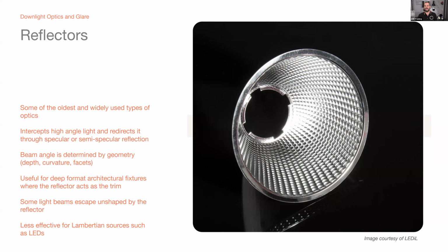Reflectors are great in that they tend to be pretty low glare because of the depth of the fixture itself. You can see, compared to the LED source size here, this depth of the reflector is very deep. So you generally get pretty good cutoff angles with reflectors.